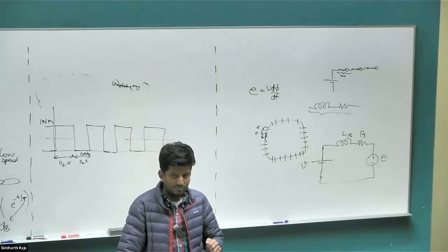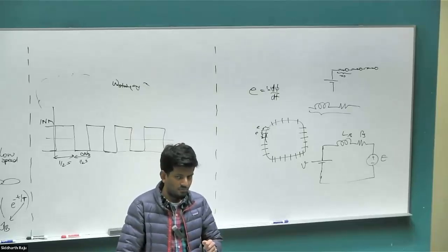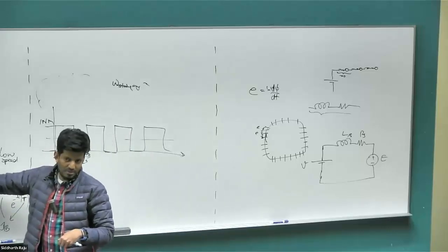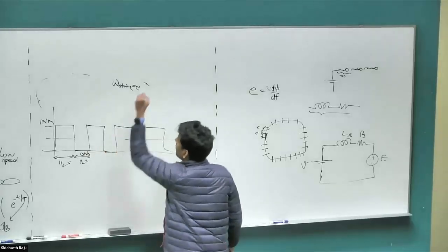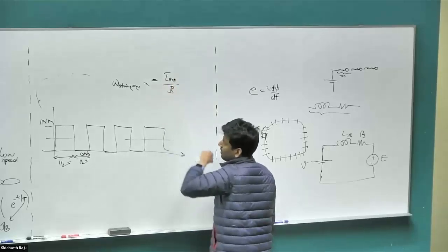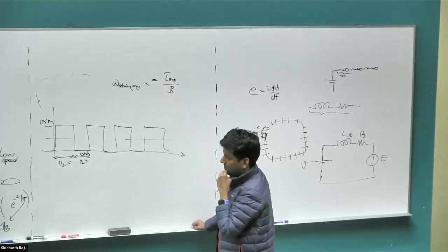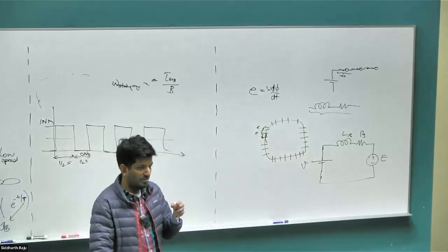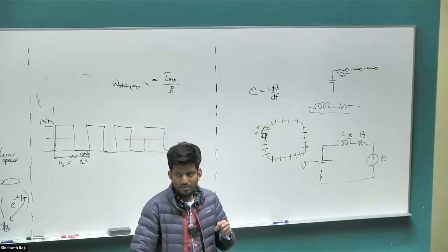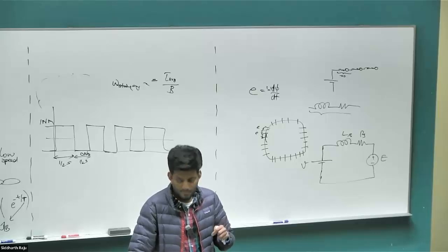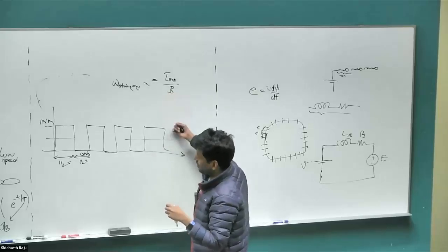How do you figure out the averages? So it's just going to be the average of the torque divided by the B value again. So omega average is going to be tau average divided by friction B. Right? Can anybody tell me why this term doesn't contribute again to the average? It'll decrease as much as it increases over time. Perfect. Another way of saying this, the average is the steady state value in some sense, right?